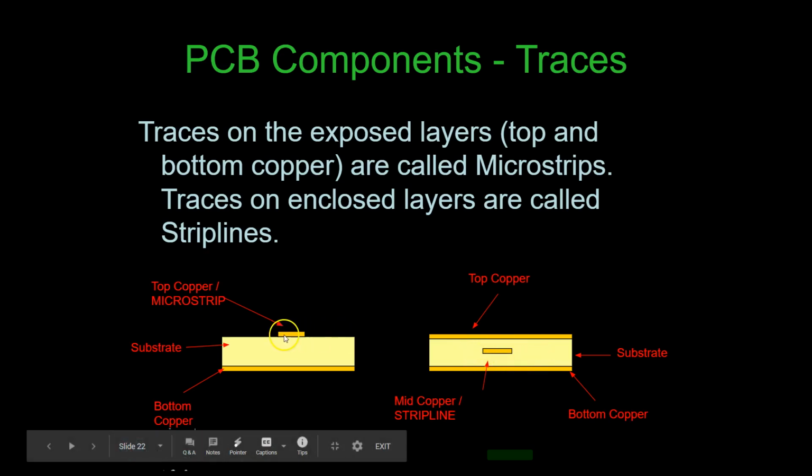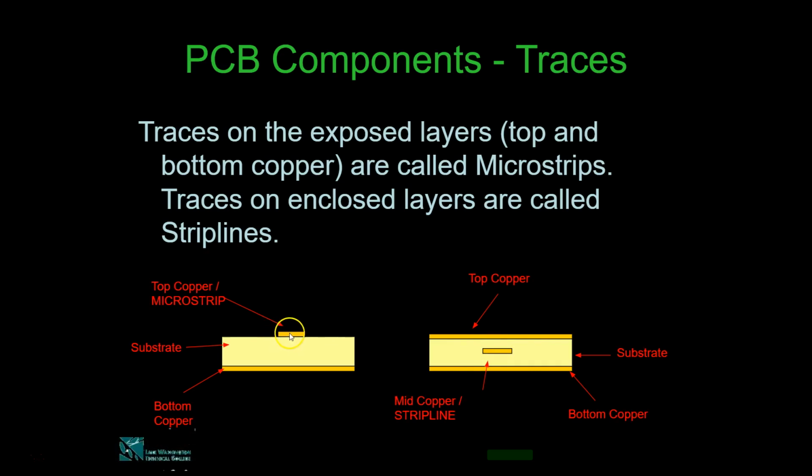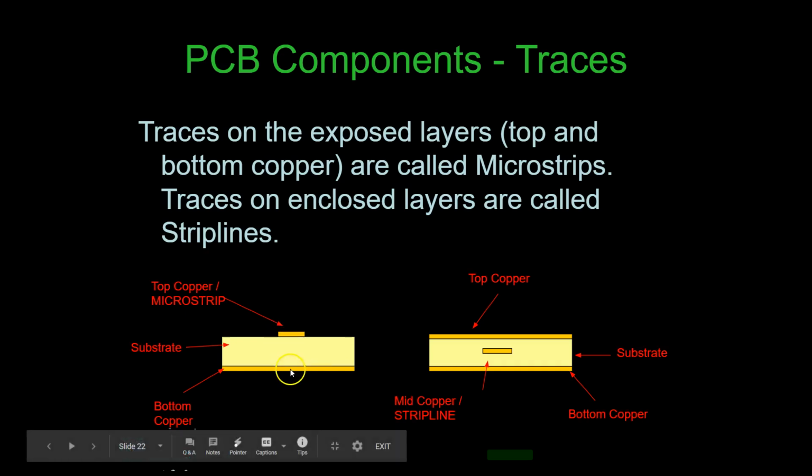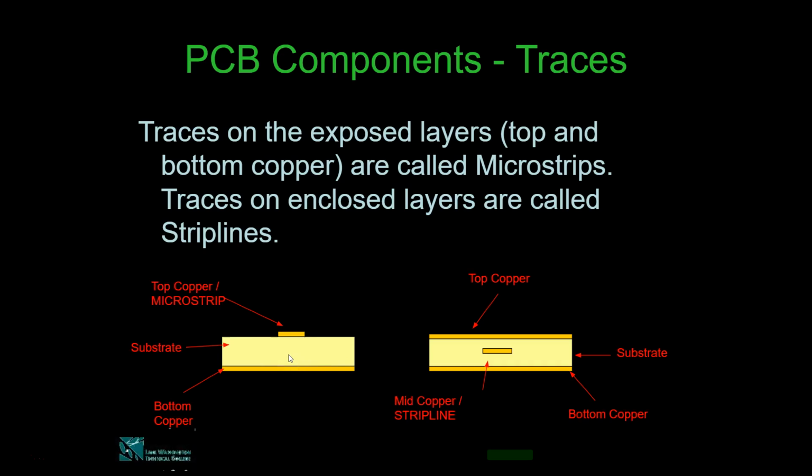And microstrip routing is a transmission line trace routed on the external layer of the board. So it is always going to be on the external layer. Because of this, it is separated from a single ground plane by a dielectric material. Now with the transmission line on the surface layer of the board, microstrip routing has better signal characteristics than strip line.